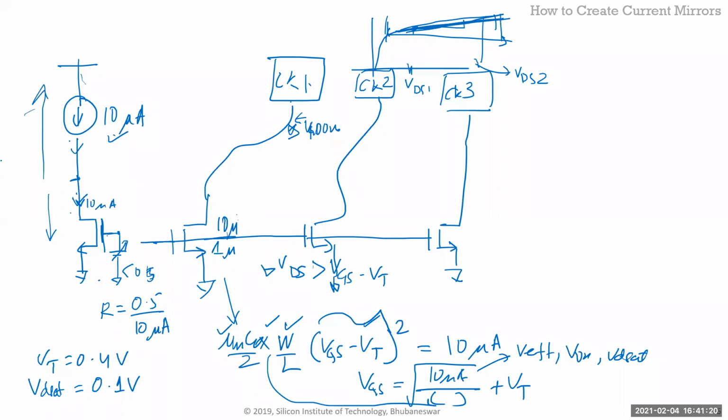So you know how this is reacting. The drain voltage is reacting. Gate and drain, exactly. If I connect this gate and drain, it's a feedback now, right? So let's start when the chip started. Chip started, everything was zero. VGS was equal to zero. And you started pumping this 10 microamp current, right? This gate is zero, ID is zero, right? Where will that current go? Because the current source is saying, I am going to send 10 microamp.